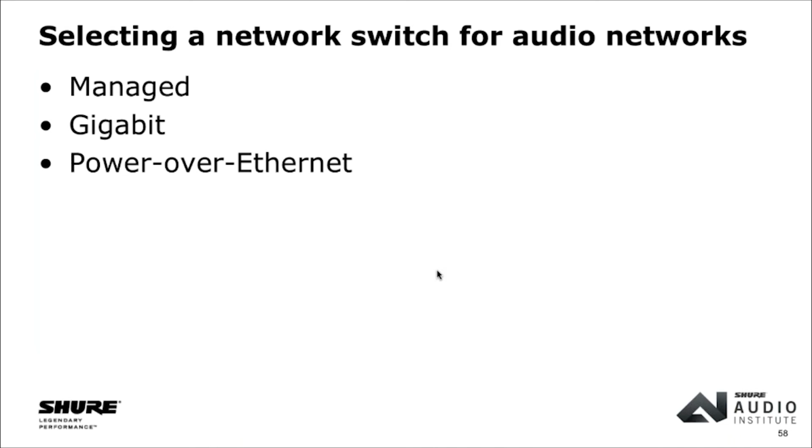The things I wanted to touch on here really relate to some specific best practices when you're putting Dante digital audio on a network. One of the most important things is making sure that you have a network switch that's up to the task. We spoke earlier about the difference between consumer and professional grade switches, and going for something a little more professional grade is typically a good idea. People often ask us, which switch should I buy? We don't really maintain a list of switches that we think are good, because there are many that are, and it would be impossible to keep that list up to date.